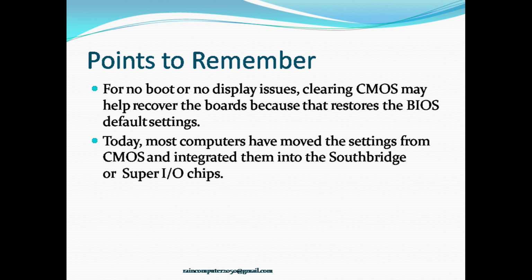For no boot or no display issues, clearing CMOS may help recover the boot because that restores the BIOS default settings. And the thing that we need to remember is most computers have moved the settings from CMOS and integrated them into the South Bridge or Super IO chips in a motherboard.